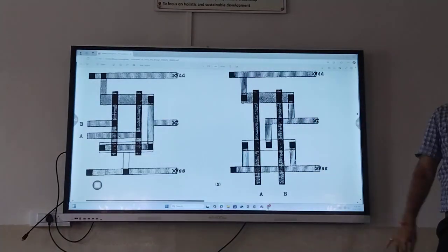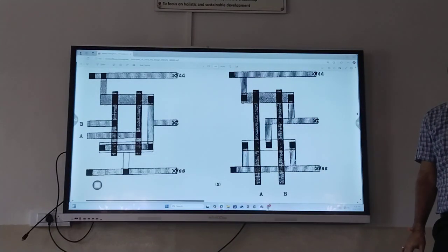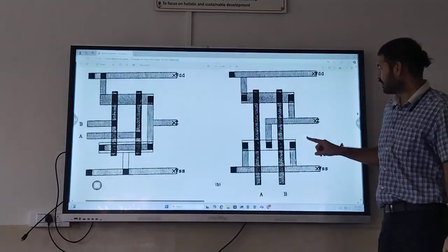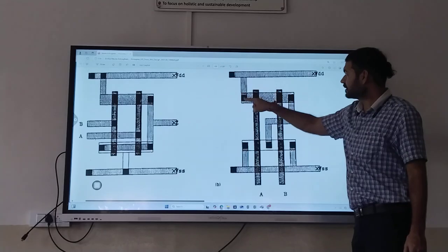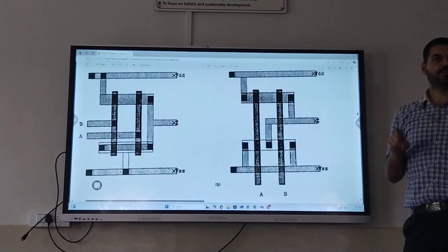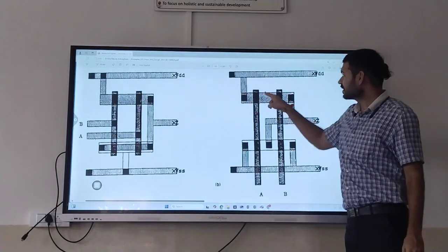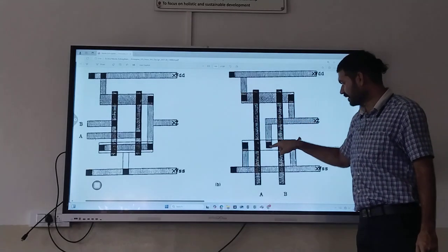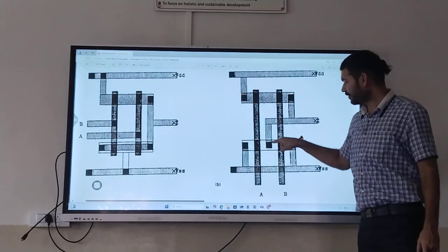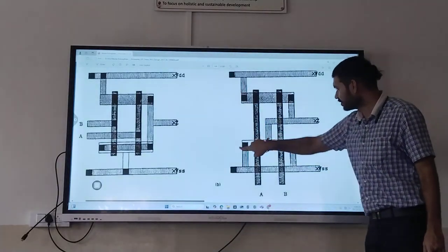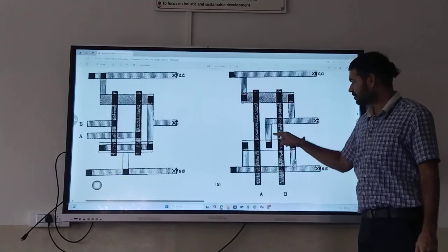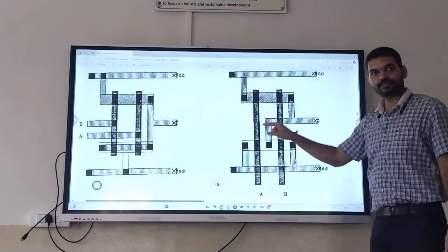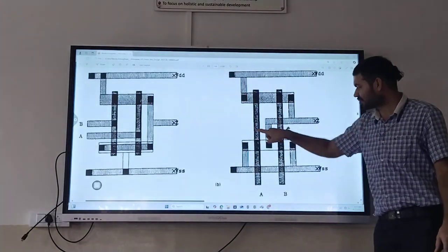Look at the difference between the two layers here. What they are doing: this is NOR, so PMOS in series, so this is source, drain to output. Okay, that drain is shorted to this drain. Here we have both the drains, so source, drain. Both the drains are shorted to the upper drain. And here the parallel connections are equal, therefore both the sources are going to VDD.